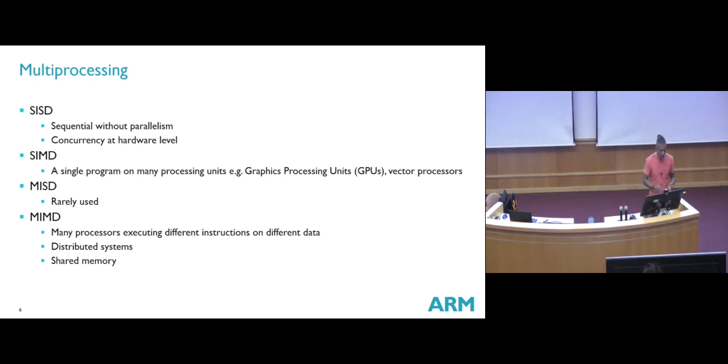In our case, we are using a single instruction with a single core, correct, with the KL25Z, but we are achieving concurrency through the OS. The OS is helping us achieve that concurrency. At the same time, we can use hardware to achieve concurrency, which is also what is happening, correct? When you configure your PWM module, once it's configured, it just generates for you. You don't need to go back and do anything. So that is concurrency at a hardware level.